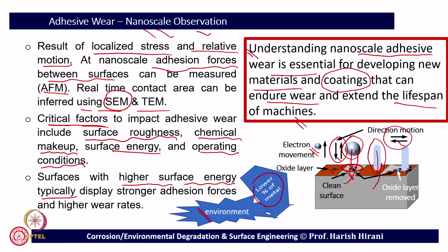Same thing with the cylindrical piece. In this case the pin comes in contact, maybe initially there is none, and then the layer is getting transferred. In this case the layer is getting transferred. So, what are the points? We can do experiments with a pin, we can do experiments with a ball, and there is also the possibility that if we adjust the relative speed, we can remove the transfer of this oxide layer completely or partly.